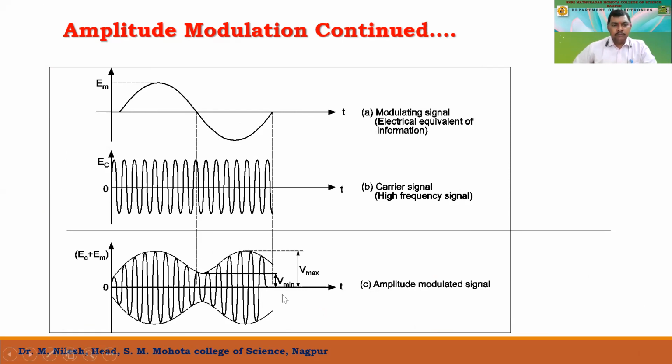So this is the envelope. Depending on the amplitude of this modulating signal, the envelope is going to vary, as shown. The modulating signal is trapped between this envelope, with the higher amplitude Vmax and Vmin. In between that, we have our original signal which we need to transfer.